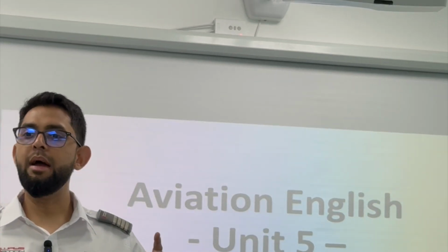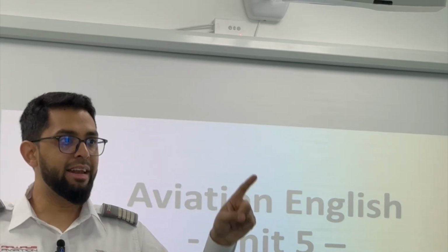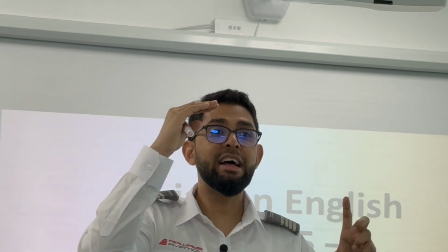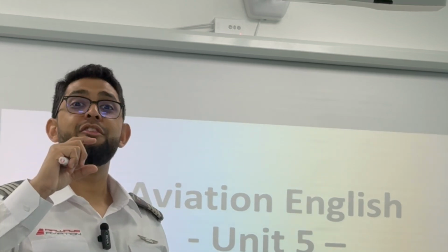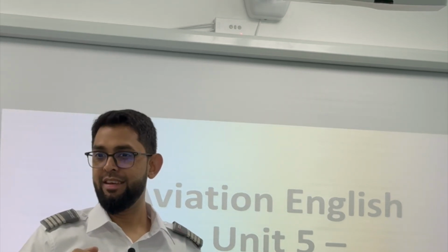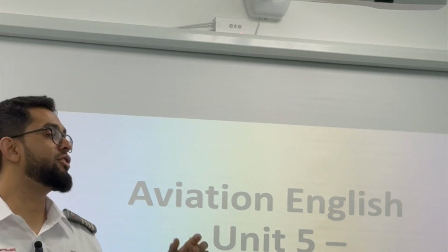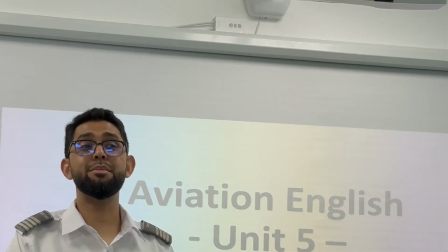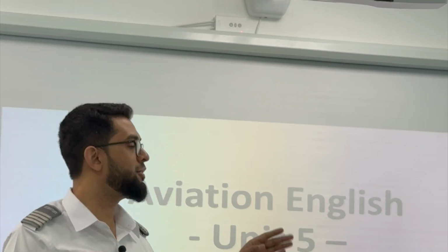Yeah, sure. I'm looking at an answer saying EICAS is a part of the cockpit instruments. It's a panel, a part of the cockpit where it has a lot of different parameters. If you look at the PowerPoint presentation, you'll see parameters such as fuel, weight, oil pressure, oil temperature, pressures of different parameters in the engine. So engine indicating crew alerting system: if something goes wrong with the systems, the fuel's running low, it will alert the crew. Does that make sense? So these are some of the most important things, EICAS.